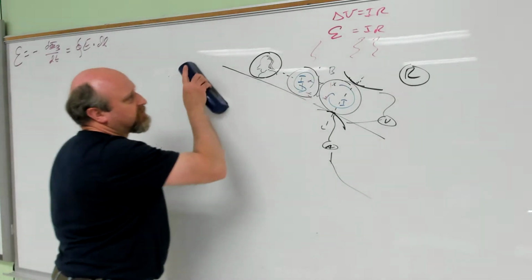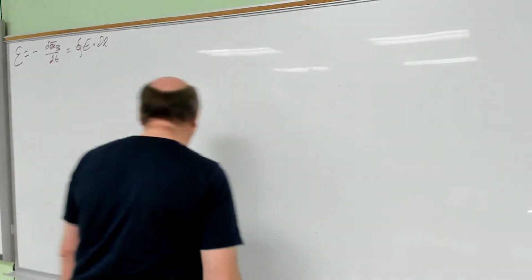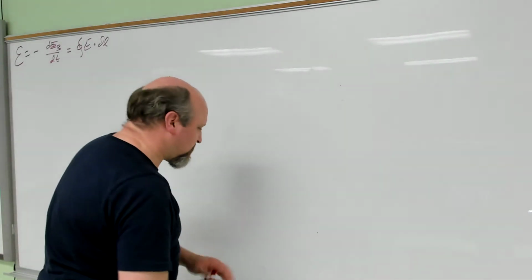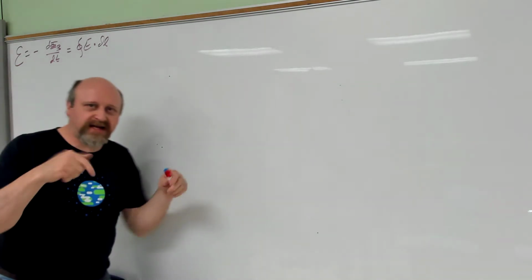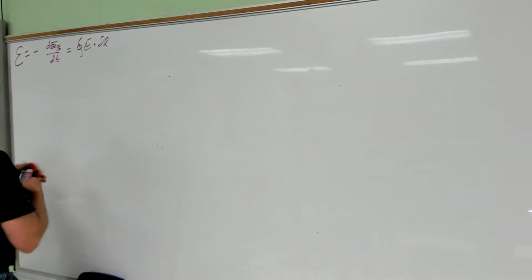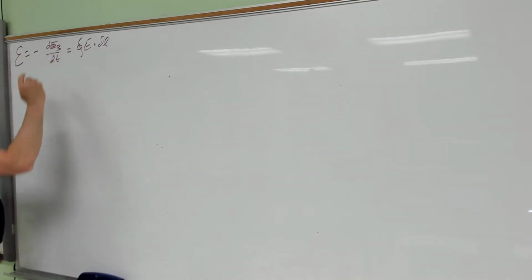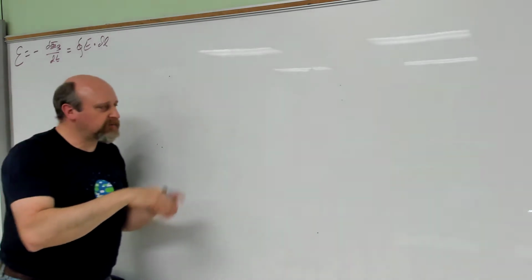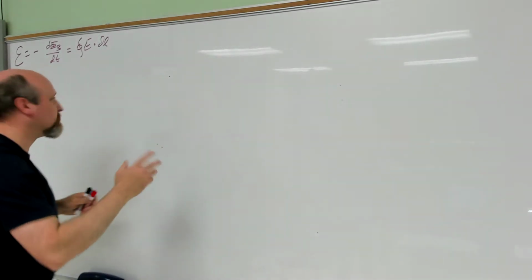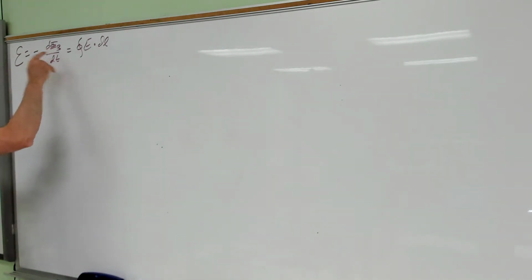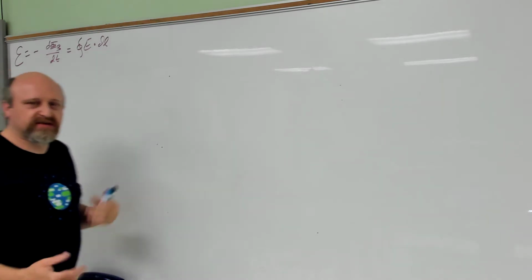Cool application of inductance, or inductors, or I should just say electromagnetic induction. Okay, getting back to where I was. What I want to point out real quick before I get on with today's lesson is that anytime I change the flux through this closed path of conductor, and it could be a solid plate of metal, or a wire in a loop or whatever, anything that changes that flux will make a voltage to fight against the change. Again, Lenz's law says that the induced voltage tries to fight against the change.